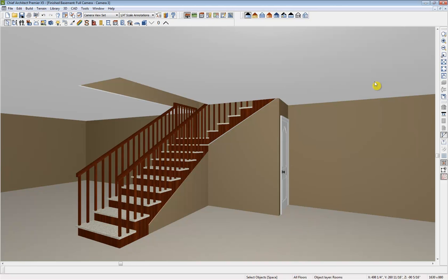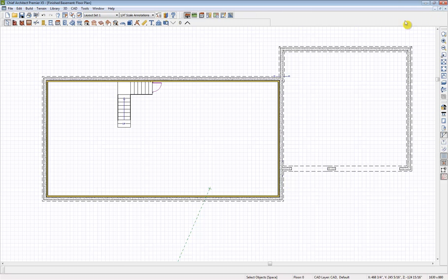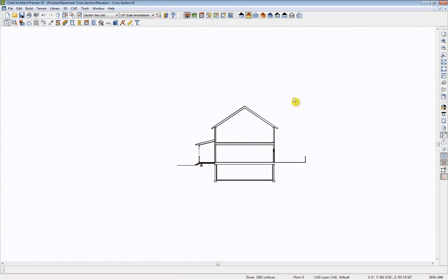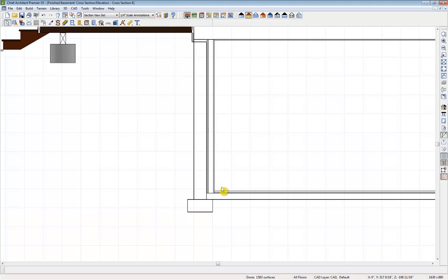There's one more area I wanted to show you, so I'm going to close out of our 3D view here and get into another camera. I'll be using this orthographic camera and the back clip cross section. So I'm just going to click and drag. We're just going to do a section. And over on the right hand toolbar I have some different zoom tools. So I'm just going to do a zoom marquee option and marquee around our foundation here.